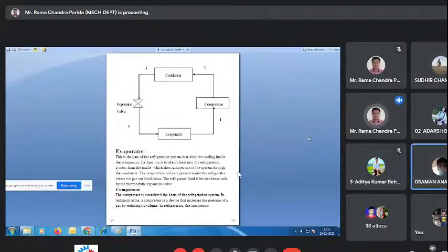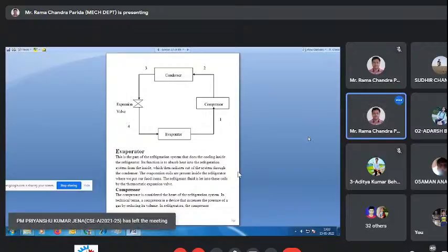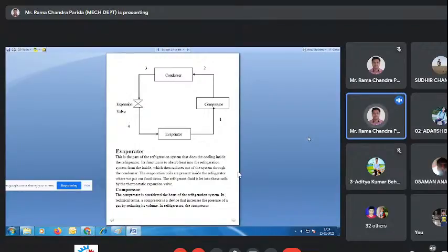So, sir, only concentrate on this diagram. Once a question comes, suppose on the refrigerator part, you have to draw this diagram. The main parts are evaporator, compressor, condenser, expansion valve. Remember, then you can explain it. Okay. So if you find what is the advantage of the vapor compression refrigeration system, it has a higher COP value.